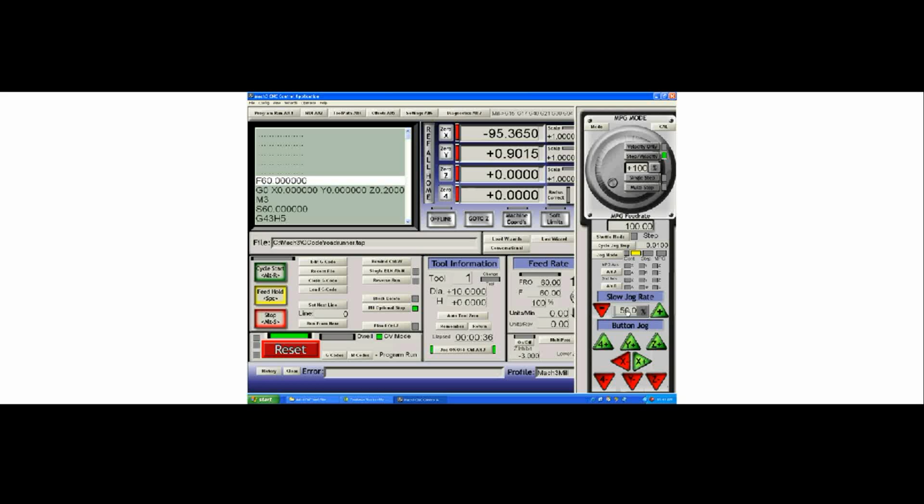This slow jog rate can be used to get very fine movement control from your arrow keys. When you want to slow things down for very fine approaches, pressing shift will take you to a high speed move so that you can move quickly away or to a piece.